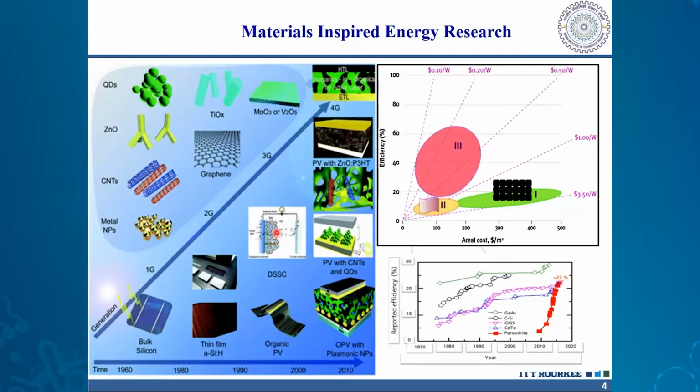So these are dye sensitized solar cells, then conducting polymer based organic solar cells. And when we combine this new kind of material with all the other existing types of solar cell, either organic or inorganic, then we get a hybrid solar cell, which is often called a fourth generation solar cell. This fourth generation includes various new types of solar cell, for example, plasmonic solar cells, singlet fission based solar cells, and also a tandem of organic and silicon, and perovskite and silicon tandem solar cells.